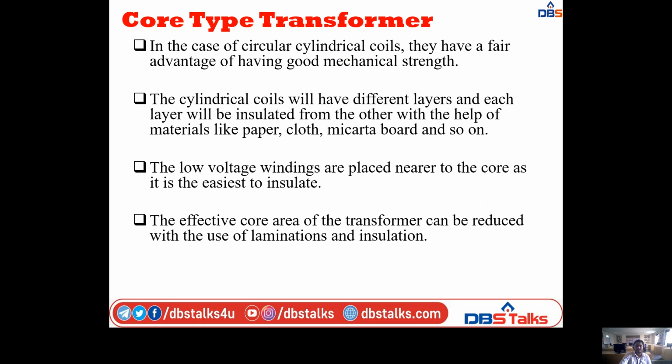In the case of circular cylindrical coils, they have a fair advantage of having good mechanical strength. The cylindrical coils will have different layers, and each layer will be insulated from the other with the help of materials like paper, cloth, mica board, and so on.